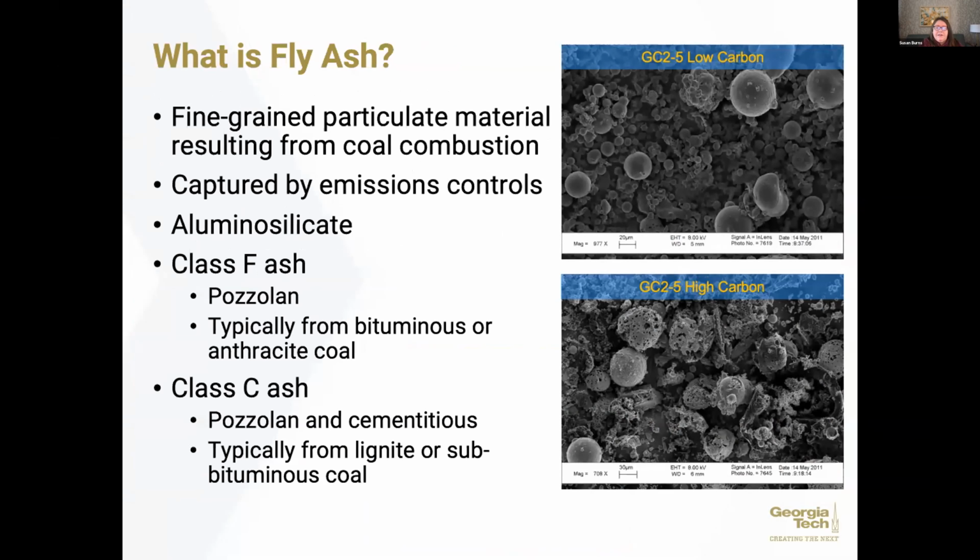What is fly ash? In particular, fly ash is the fine-grained particulate material that results from coal combustion. It is the ash that flies up the flue. We capture it by emissions controls, which have become more strict in the United States over the last few decades. So it's a very lightweight, low density material. It is an aluminosilicate.